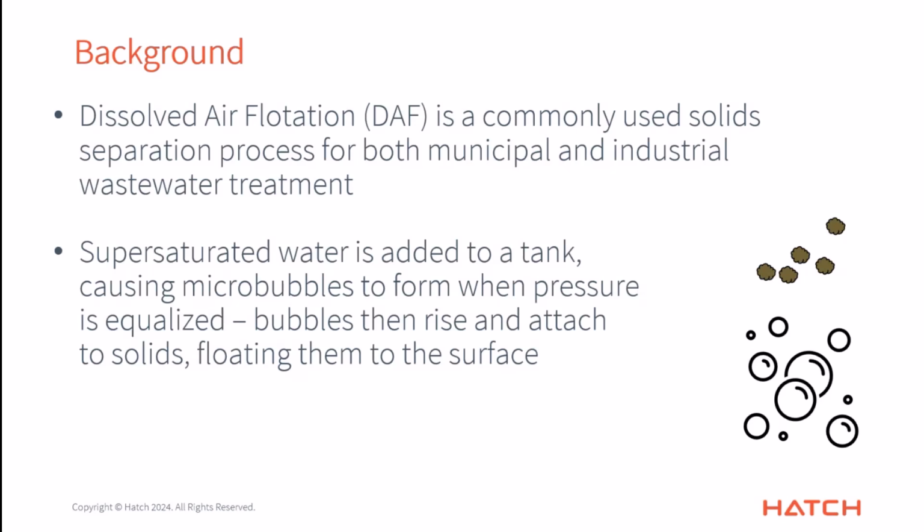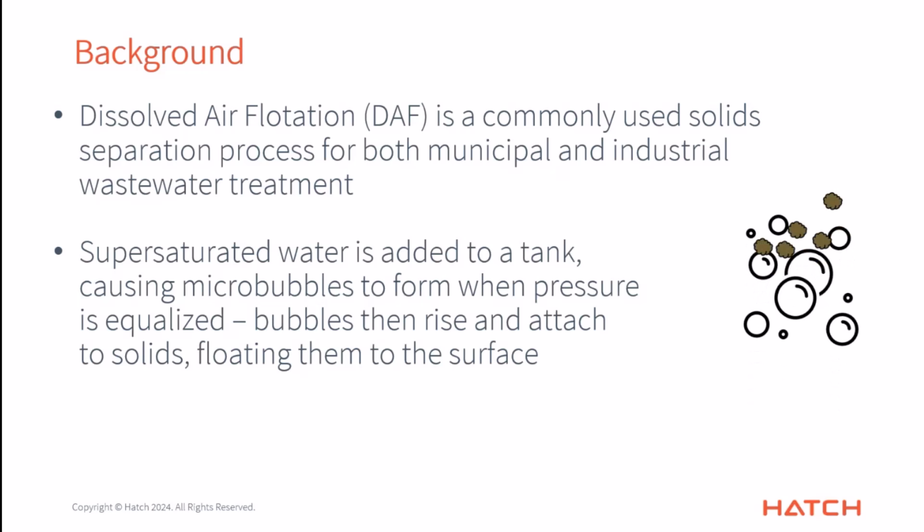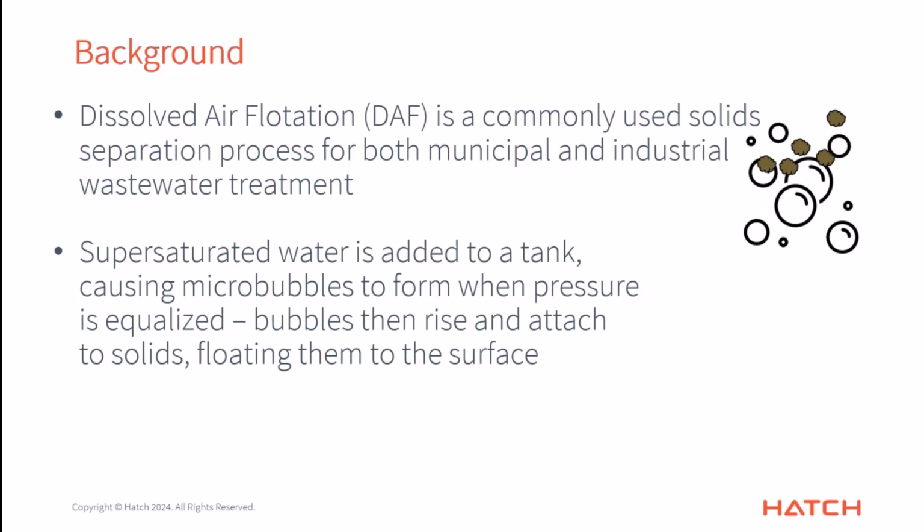You are feeding your solids into it through the flow of your influent, and at that same time you're also feeding a supersaturated water, supersaturated with air, such that when it comes into the tank, and that tank is equalized in terms of pressure with the atmosphere, micro bubbles will come out of solution immediately and form in the tank that you have. And then those bubbles will, of course, rise automatically, and they'll capture the solids and other things as they go, and then carry those to the top.